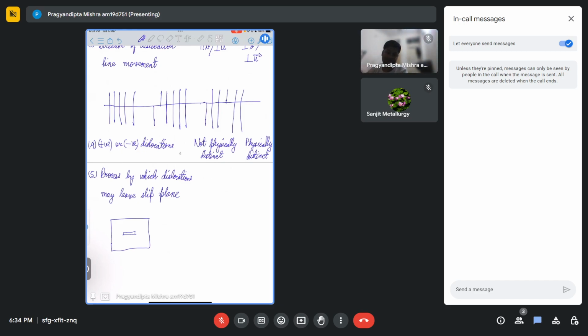So from the top, this edge dislocation will look like a small defect. How can it leave that particular plane is what we are now looking at. So there are different ways it can leave. It can slip to a newer plane, right? So it can slip like this, or it can climb, it can go up down, right? So that is also leaving the slip plane, it is moving to a newer plane.